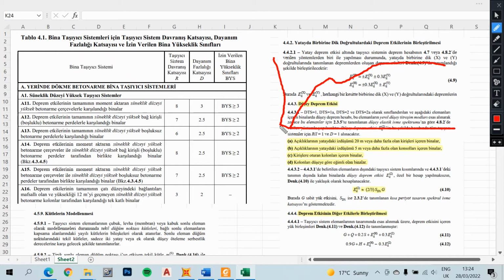But when we define the steel material in the program, you only define this part, the elastic part. But we also have a high amount here, right? The maximum stress of the steel actually goes up to here, but we only consider this part. So in reality there is some excess of the material strength, but we didn't consider it. So this D factor actually stands for that excess, the material excess that we didn't consider.